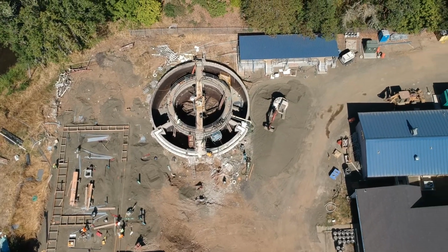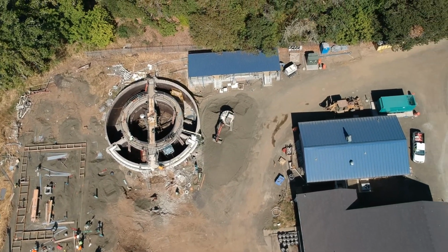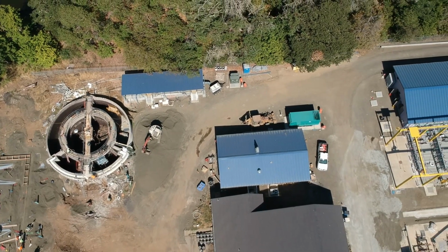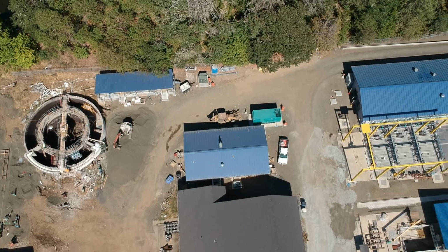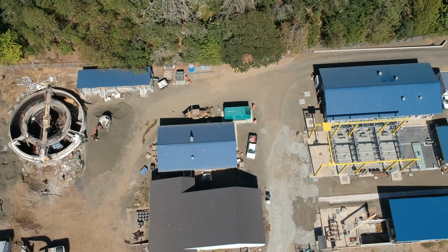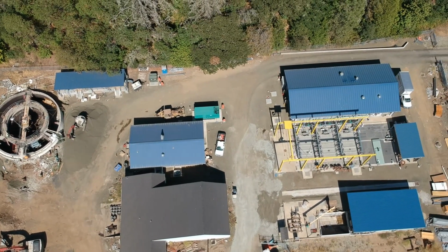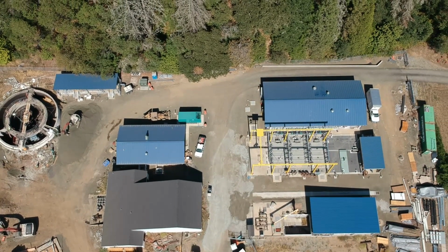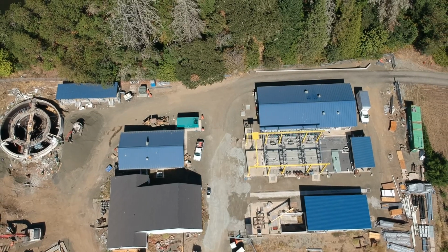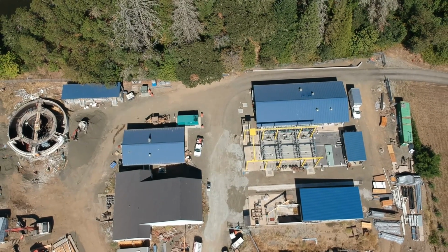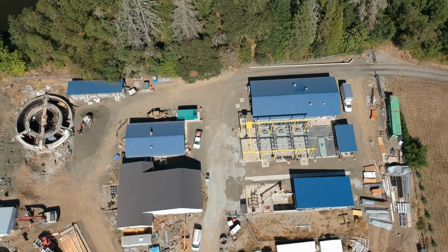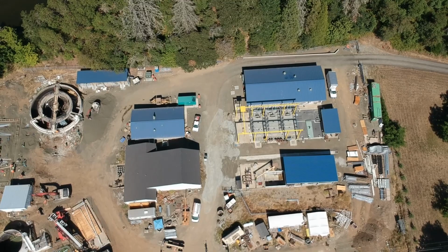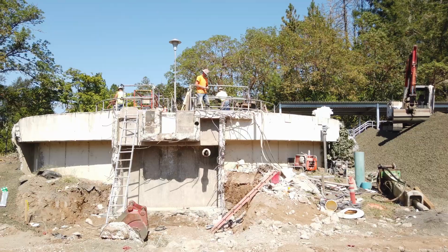Construction operations are currently focused on solids management systems. Waste-activated sludge from the MBR will ultimately be conveyed to an aerobic digester. The city's previous activated sludge system will be converted to an aerobic digester with a membrane thickener. The aerobic digester will include an air diffuser system and pH probes for aeration control. Thickened solids from the aerobic digester will typically be sent to a dewatering building.